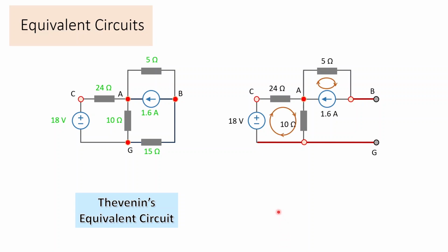To get the Thevenin volts, we basically just consider what's going on with the circuit without the output, an open circuit output. And we see that in this particular case, we have two loops that are joined only at one node. There's not a return. In other words, no current can flow from one loop to the other because there's no pathway back. So these are separate loops. And so the Thevenin volts from G to B, we can say, it's the volts increase across the 10 ohms minus the volts decrease across the 5 ohms.